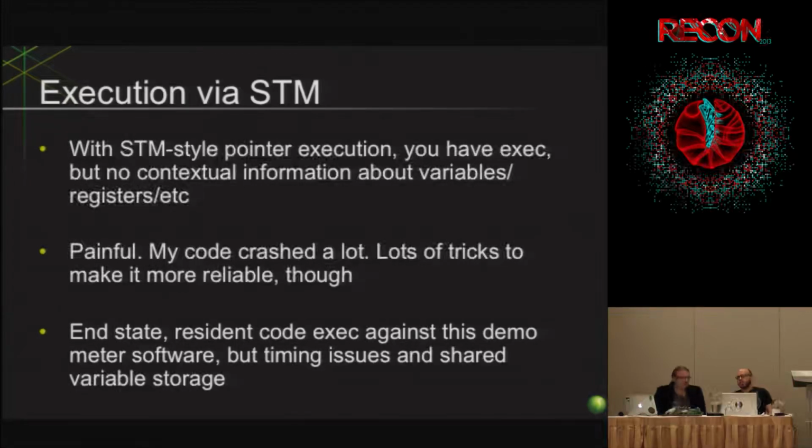So there are different things you can do to try to make it more stable. You can shorten those timing windows as much as you can. There are other ways that you can disable interrupts. In some cases, depending on how it's firing, if you disable interrupts, then it will no longer process your input, which would really suck. So there are things like that to look for, at least, if you're having a stability problem.